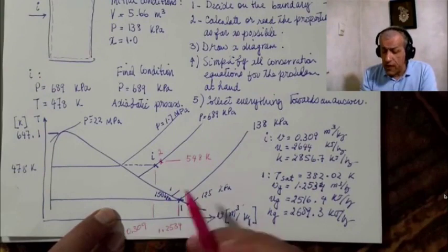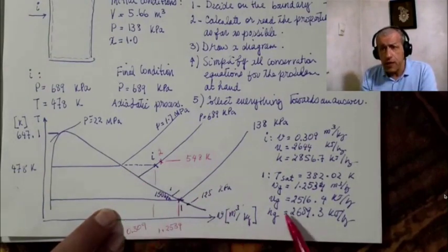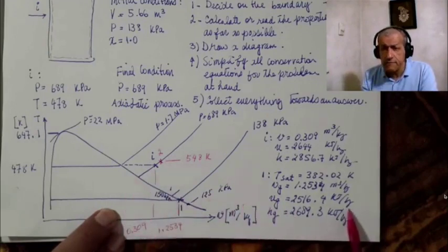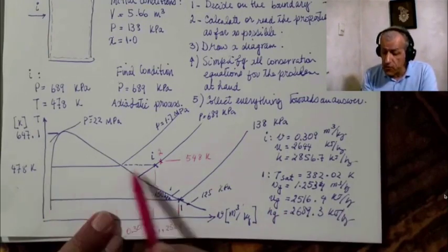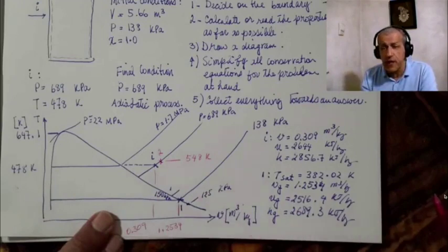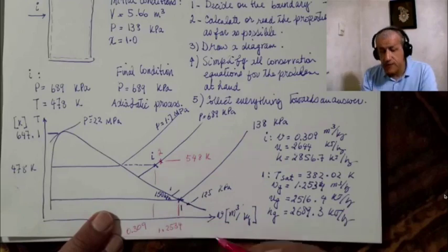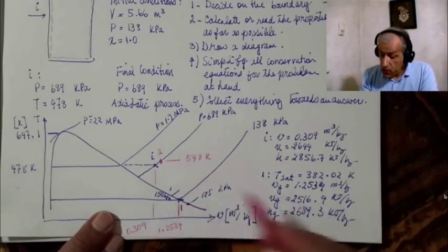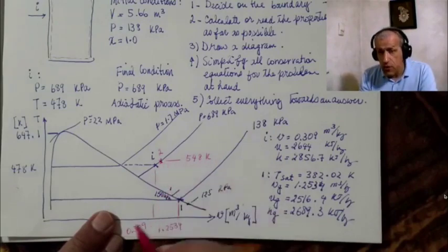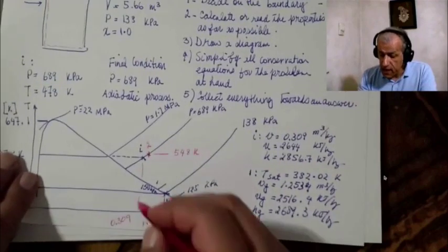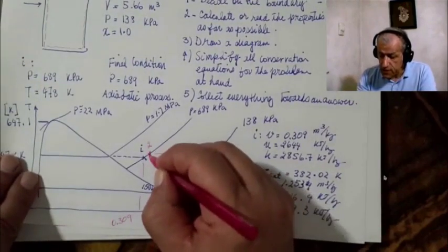So in fact, we should have given such a slope here that it would end up somewhere like here, far away, four times this distance. We should have to go further right to find the right point for Vg at this point. And that's why when I wanted to draw point 2, where the specific volume is 0.36, I had to be very careful. It's somewhere here.